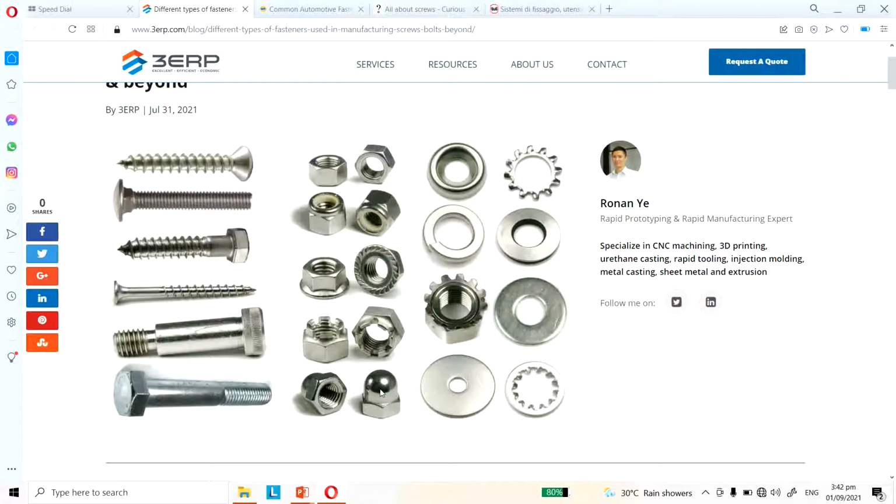I've also seen this in engine parts. And so it's a castellated nut, a dome nut. And for washers, there are also many types. Right here we have a flat washer, and also this type of washer, which has a wider area as compared to this one, because there are types like, for example, fender type washers or SAE type washers.